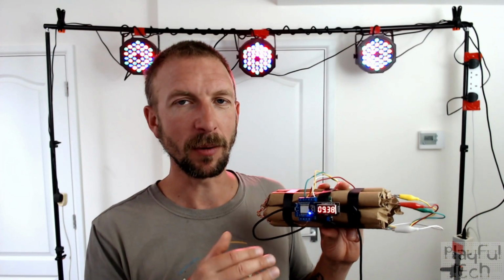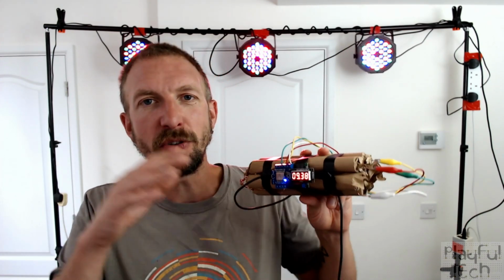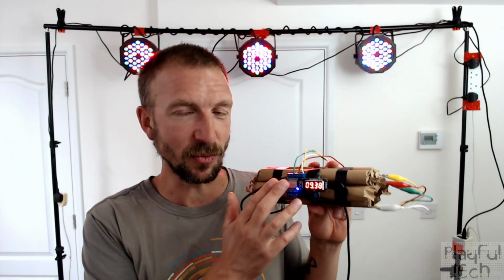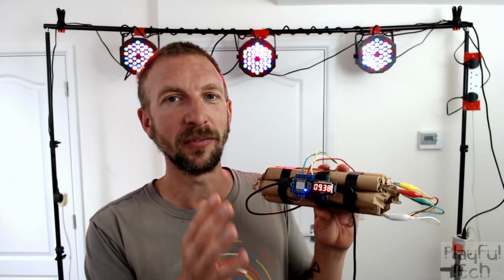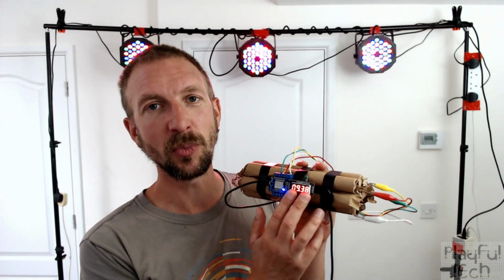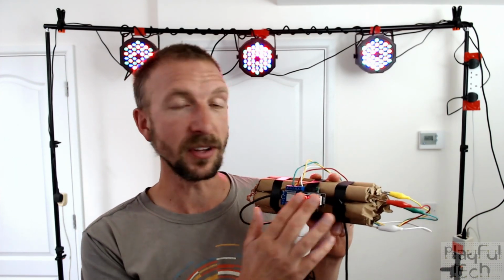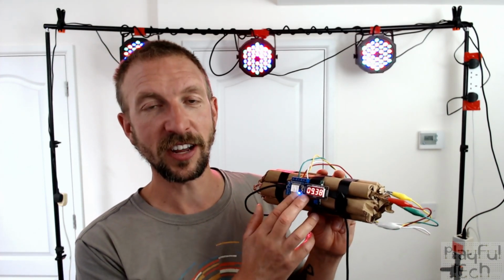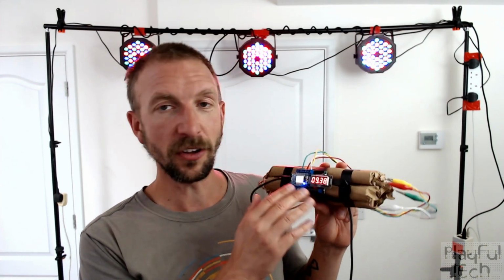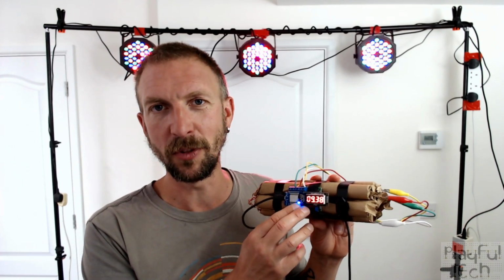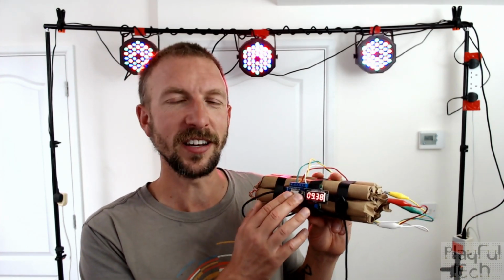I'll show you the wiring diagram, but just be aware you can't simply replace all of your existing Arduino projects with one of these boards without doing a little bit of rejigging of what goes where. The display here is a TM1637 display. They're very common. I've used these in lots of projects as well. This is wired to 5 volt, to ground, and to a clock and a data line. There's nothing special about those pins at all, so for those I used some of the pins that were a little bit more constrained, I guess.